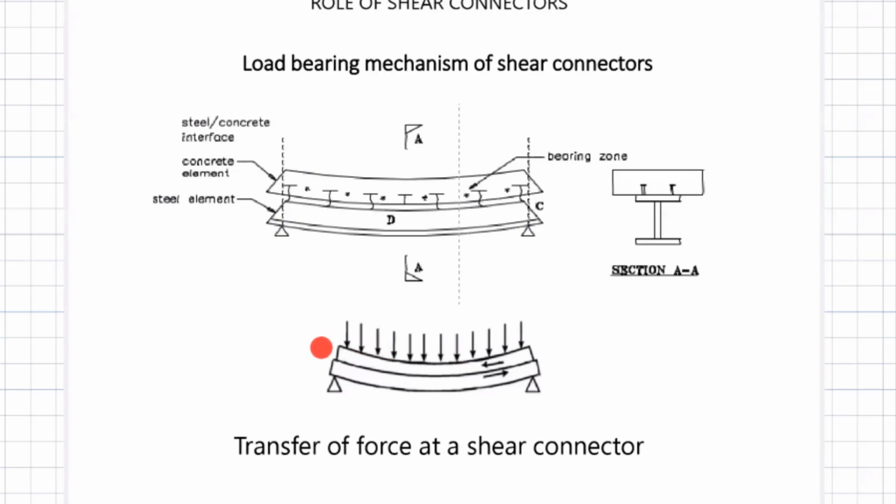Now, for a minute, you reverse. You imagine the top one is going to be steel. I'm giving a situation hypothetically. So let's say I have a steel beam on top, and I have concrete. You will find a separation that takes place between these two members. So since the material underneath has a lesser modulus, it will deflect more compared to the steel.